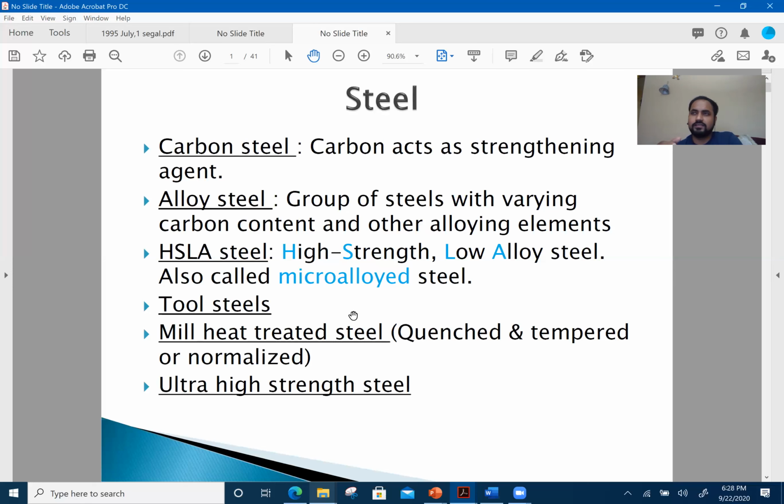You just enter the elements that you're looking for, and you will find a bunch of phase diagrams. That can be a technique to figure out which alloying element will work for this composition. And of course, we can get some of Dr. Aryave's students to help us with Thermo-Calc and CALPHAD if we need that to model the alloy.